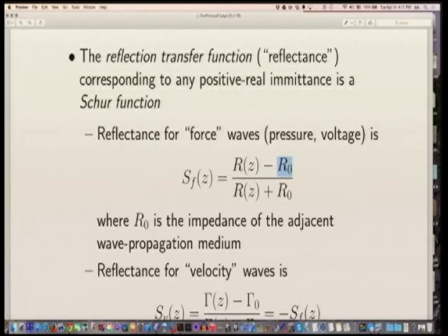So a wave travels in some impedance, and the voltage part equals the impedance times the current part. As we've mentioned, when the impedance changes, you get reflection, and this is the reflection coefficient. If you're reflecting off of a complex impedance, some big one-port impedance, it can be any number of poles and zeros, then the reflection transfer function is calculated like this. We're going to derive this and develop this stuff from the ground up. But right now I'm just going to give you the formula, because it's worth memorizing. It comes up so often.